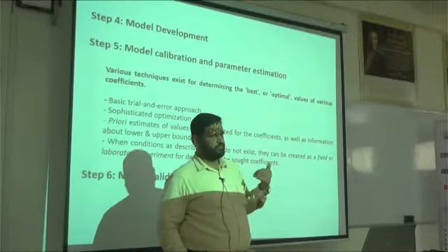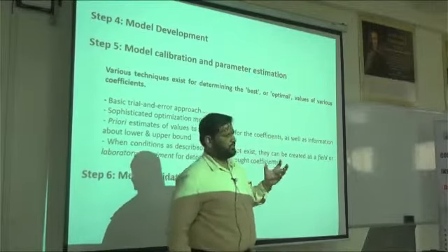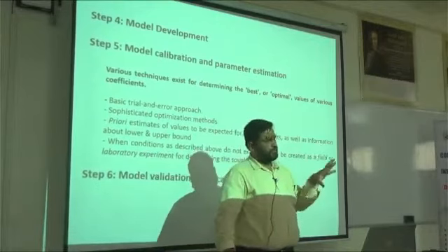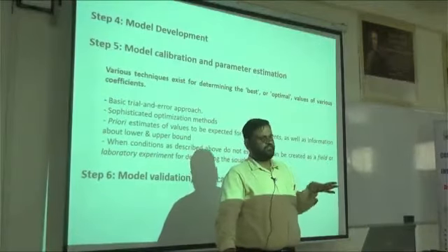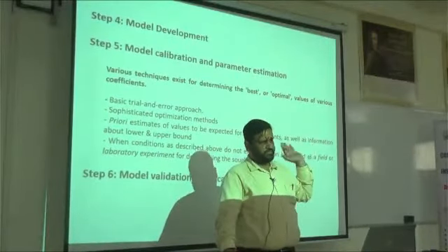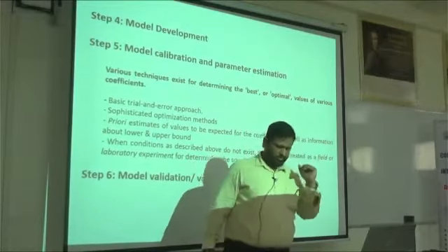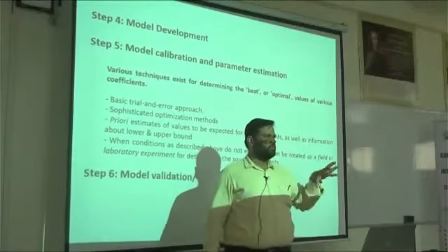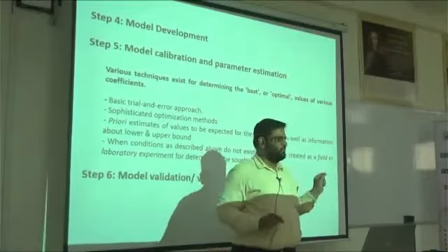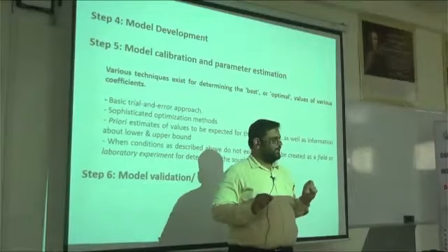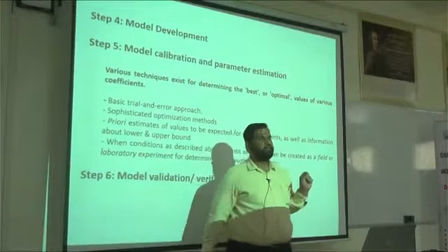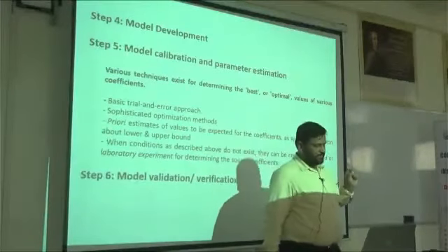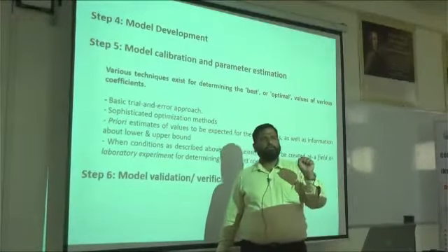Ungauged catchments are also there. For those ungauged catchments, they won't measure; some kind of advanced techniques are also there for measuring the discharge and all these things. So once you have developed your model and got that output, you have to match that output with your observed data, and then compute some kind of statistics. That is known as your model calibration.